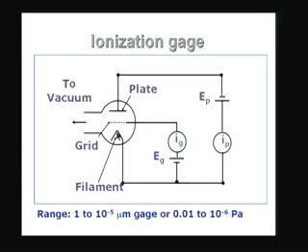Actually, it is going to glow like the filament in a bulb, and therefore, it is going to be quite hot. There is one type of ion gauge where the temperature of the filament is high, and it is the hot cathode which is going to give out electrons. The electrons are going to be released by thermionic emission. And let us see what happens to these electrons.